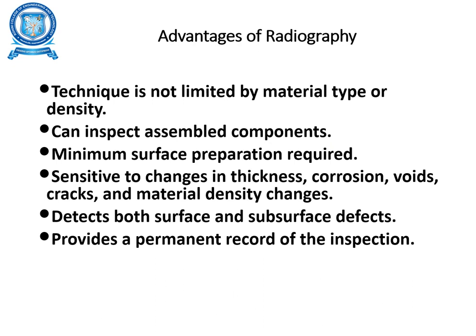Coming to the advantages of radiography, it is not limited by material type or density, and it can inspect assembled components. Minimum surface preparation is required, and it is very sensitive to changes in thickness, corrosion, cracks, and material density changes. It can detect surface and subsurface defects, and it provides a permanent record of the inspection.